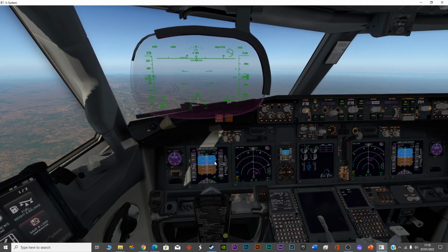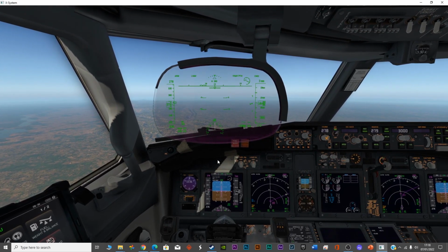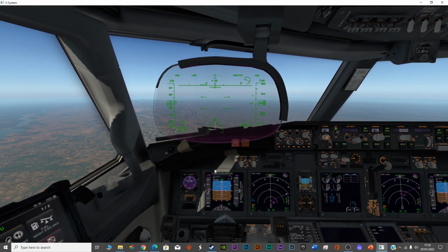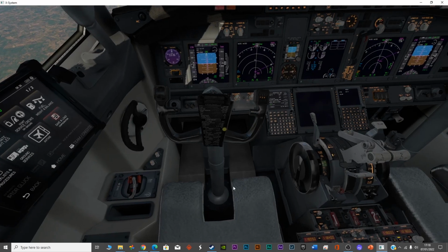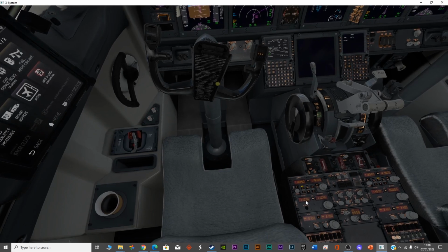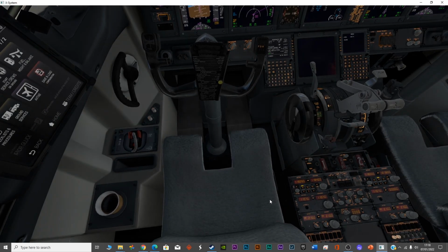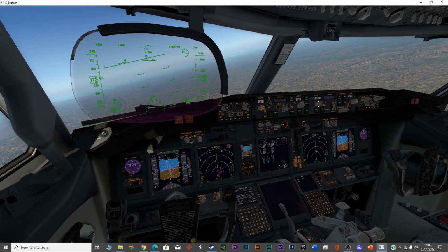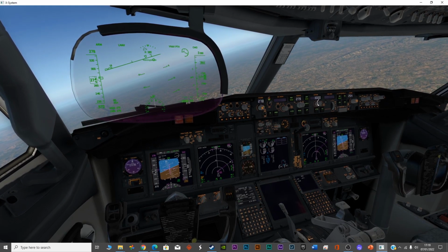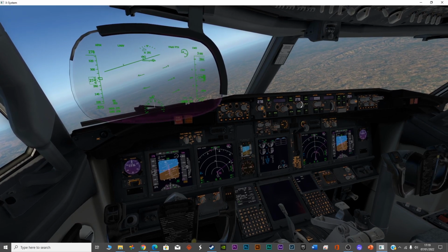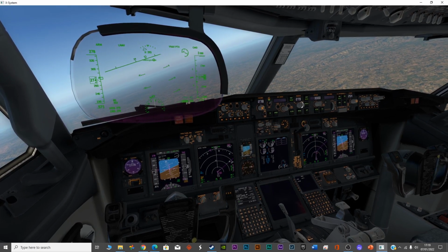Speed is under control. We don't have any error coming up, and everything is looking good so far. Not a big issue. So ILS frequency is there. Let's do this check once again. ILS frequency is there. The glide slope for ILS intercept is at 3,000 feet, which is entered. Heading for the runway is 279.